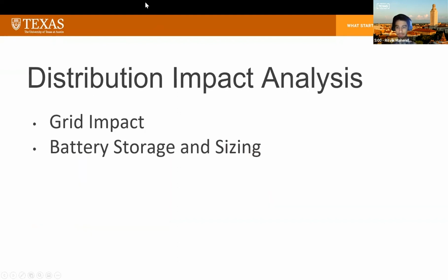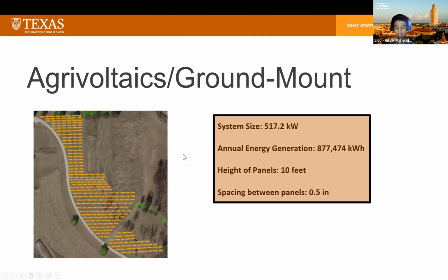As for our ground mount system, we designed it on the east side fields next to the Law College. We set a height of about 10 panels because we were putting this mostly over grass, which is pretty short. We decided to avoid any taller crops like wheat or corn because taller crops would need taller structures, which are more expensive. We also decided to put a spacing of about 14 feet to avoid any unnecessary shading to the grass. And we also avoided any research fields that were for the university in this area so that we wouldn't disrupt any ongoing research for the university.